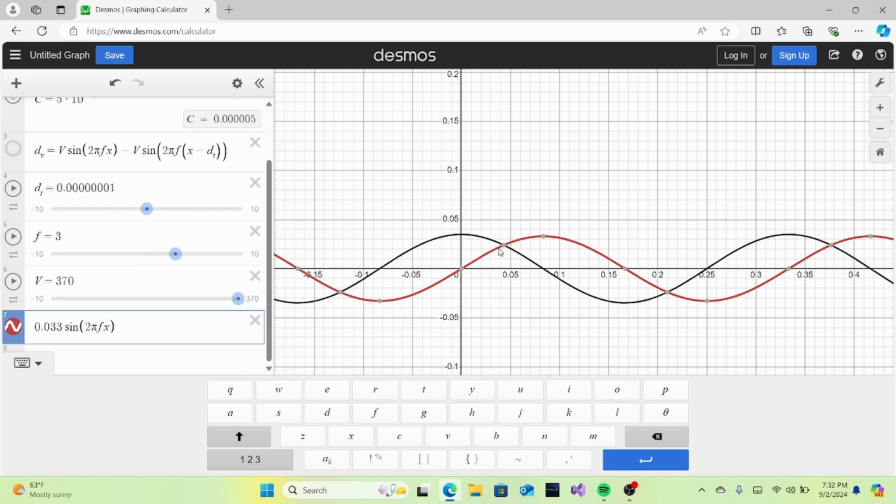So if you were to take the derivative of a sine function like we were just saying, the rate of change is greatest at 0, which means our current will peak at 0. And then, as the rate of change begins to fall, it falls to 0 at the peak. And so our derivative is 0 here. That means that basically the derivative of a sine function is equivalent to a cosine function. The only difference between sine and cosine really is that cosine begins at a peak. At 90 degrees, the cosine of 90 is always 0, but the cosine of 0 is always the peak. It's the opposite with the sine function. The sine of 0 equals 0, and the sine of 90 degrees is equal to the peak. So that's basically why.